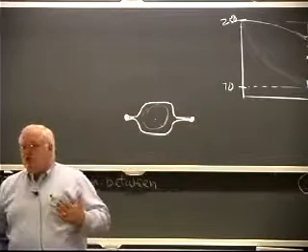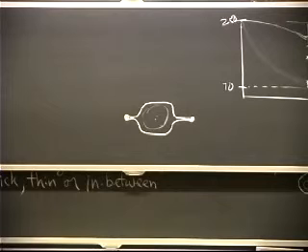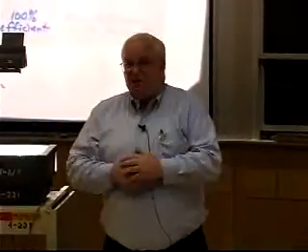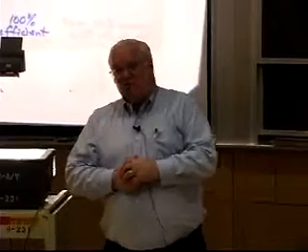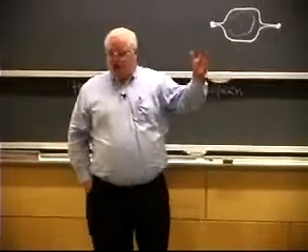Well, you could do that. You can do a beautiful job with gas tungsten arc at 6 inches a minute, maybe 10 inches a minute. That means for a typical catalytic converter, that might be 2-3 minutes worth of welding time with a fast gas tungsten arc. Plus, you got all the maintenance on the tungsten electrodes, you may have to replace those every 30 minutes.